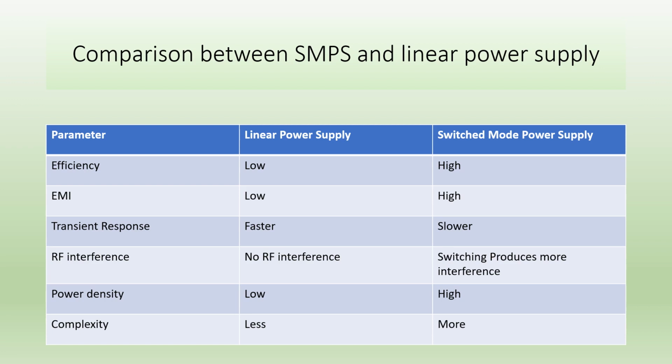So if we keep constant magnetic flux and number of turns, then induced EMF is directly proportional to frequency. That means your power rating is directly proportional to frequency. If you increase the frequency, your power rating will increase.